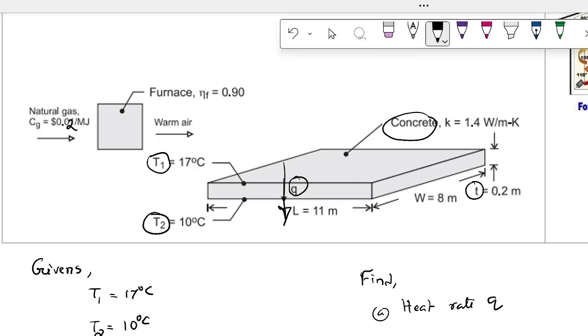All right. What are the assumptions here? The three assumptions that I want to write. Anybody have any idea about the assumptions? We're not going to deal with radiation in this problem because they didn't give you the emissivity. Anytime they give you the emissivity, you're going to deal with that. So it's just the conduction. The first assumption is steady state conduction. Steady state means, you remember from thermo class, with time the heat rate doesn't change. If the heat rate at this point during the class time is whatever amount of watt or kilowatt, tomorrow same time same heat rate, tonight same heat rate, every time same heat rate for an infinite amount of time. That's called steady state. So that's the first assumption. Those who took thermo, anytime I write SS it means steady state, short form.